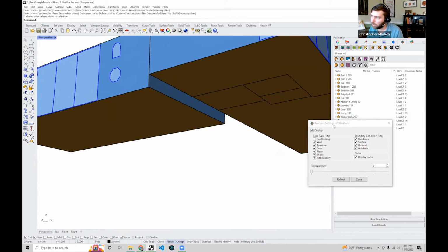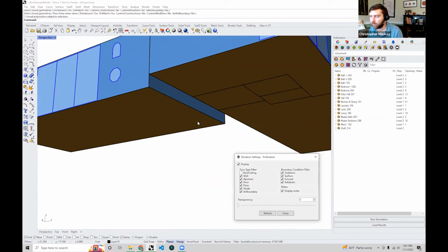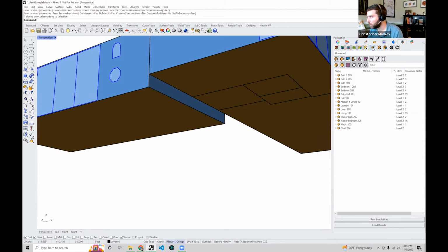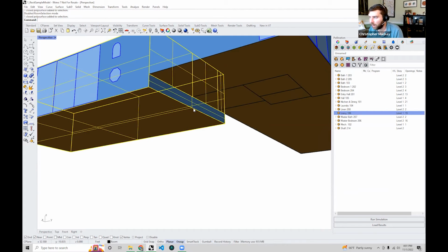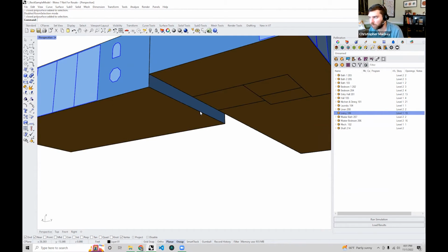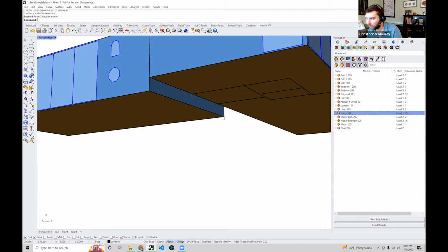There are a few different ways to select an individual face. This is going to be a review at this point. We can certainly turn off room selection, or if we hold down Control and Shift, we can use that to select an individual room surface. That's one way of doing it. I like to leave the room selection on because, especially when you're just learning, it's good. It's like bumpers, to use an analogy with bowling, to keep you from editing things you don't mean to.